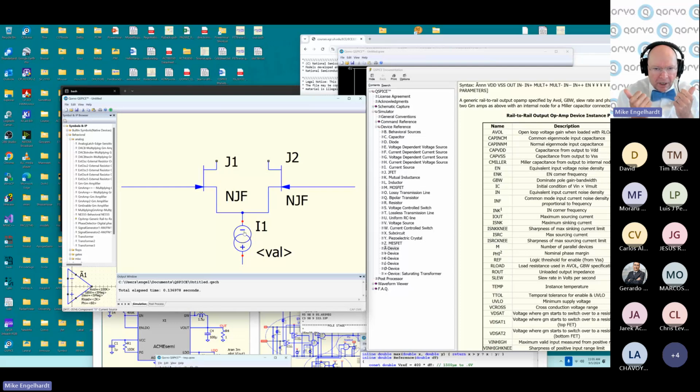And so if the impedance on both of these are the same, like you make a classic instrumentation amplifier with 4 resistors and 1 op amp, then the impedance seen on each input is the same, and that common mode current is read out to a common mode voltage,